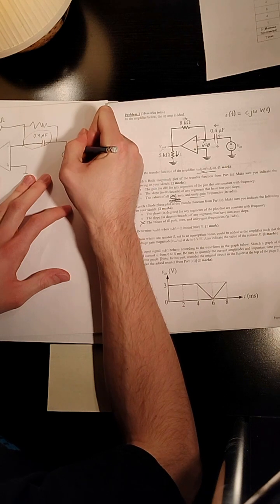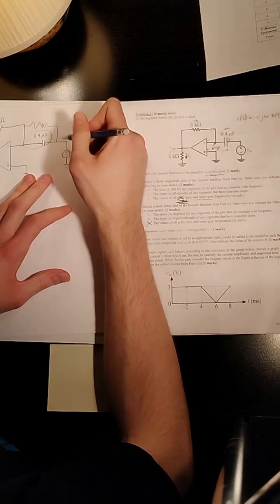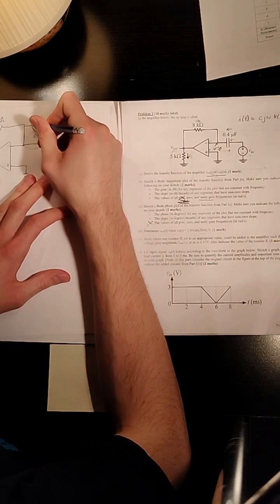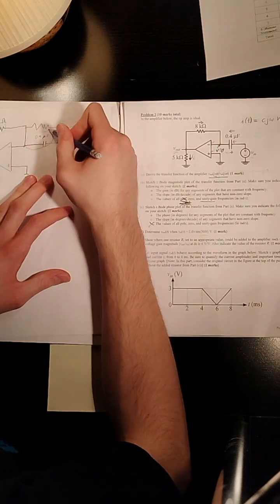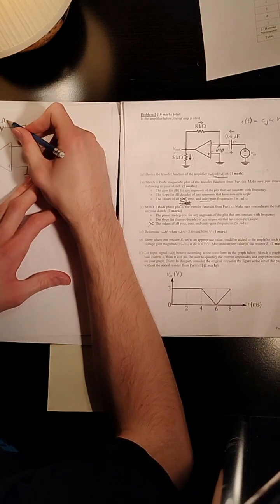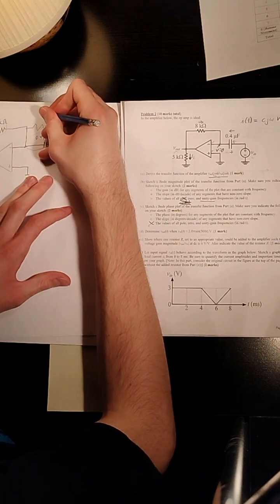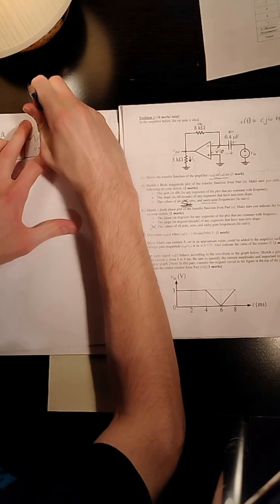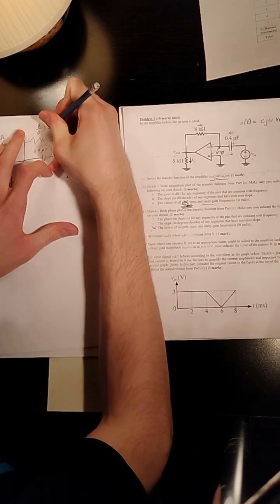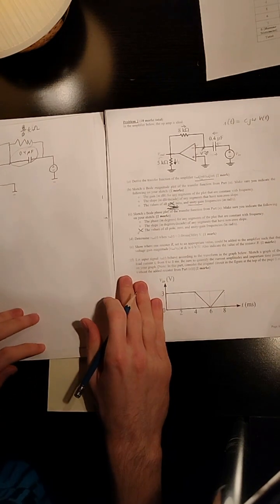And basically, you're going to get the same current through both of these. And you want it to lose 6 times more voltage here than you want it to lose here. So the resistance of this one needs to be 1/6 of the resistance of this one. So this would be 8 over 6 kiloohms. And that would be what I would add to the circuit.